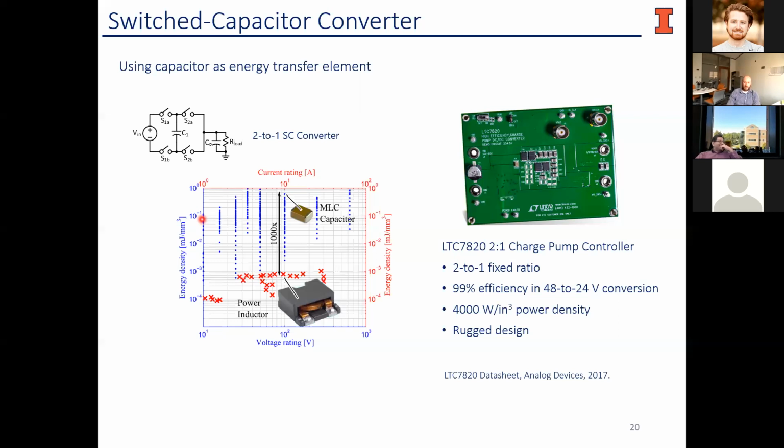And it's also very difficult because research is looking at more power inductors that do have higher power energy density per area, but they're looking at it on a very small scale. And maybe they're looking at some of these racetrack inductors or different things that you'll see for on-chip inductors. But this also doesn't really capture the quality of these capacitors or these inductors either, right? When it comes to their ESR and everything else along those lines. So it is a challenge, right?